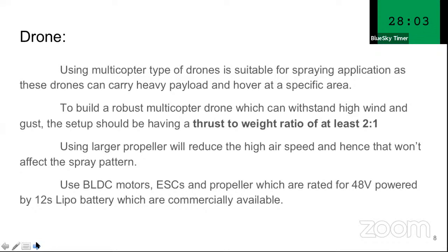Using larger propellers will reduce the high air speed pushed down from the propeller, and hence that won't affect the spray pattern. That's one of the key things we have to keep in mind: will the propeller flow affect the spray pattern, and is that okay? In some cases, it's okay for the spray pattern to be affected by the propeller flow, and in some cases, it is not okay, right? We'll see some of those in greater detail.